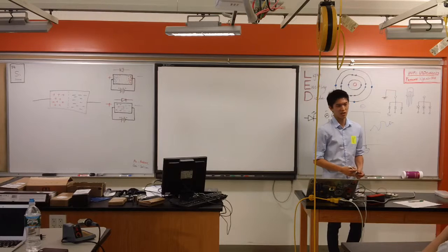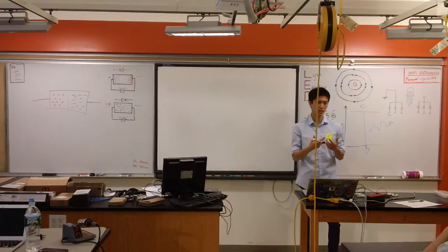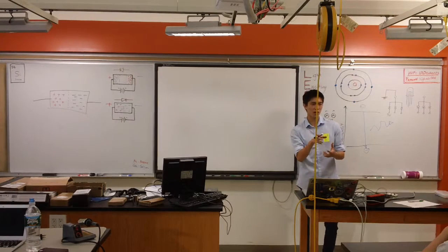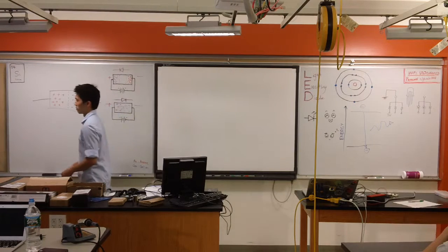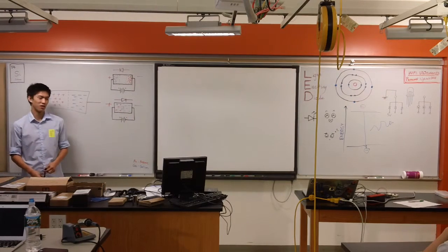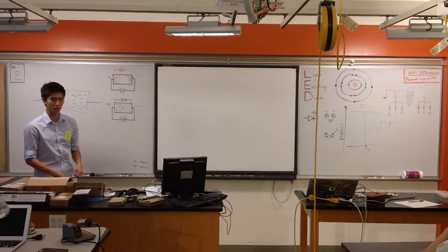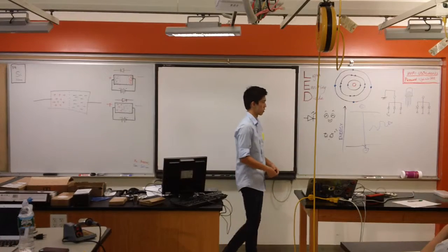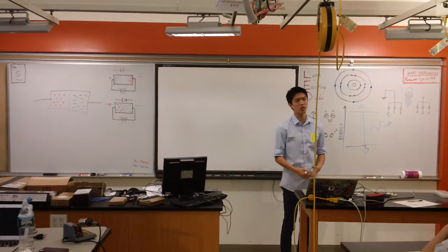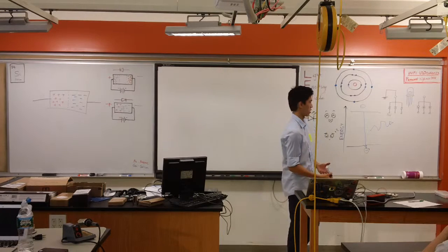Right. Ground voltage. Yeah, so the dopants in the silicon separate out, and they form a barrier known as the depletion zone. You guys probably won't have to hear this word again until college, but the bit in the middle is called the depletion zone. The reason it's called that is because the semiconductor is depleted of its charge carriers, so it can no longer carry electricity, and therefore current doesn't flow.